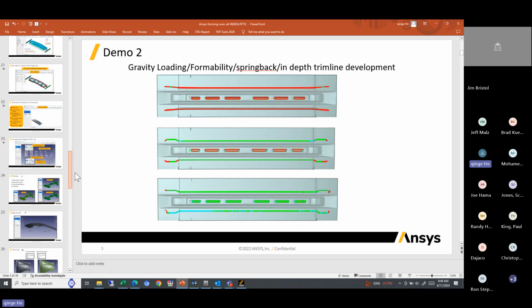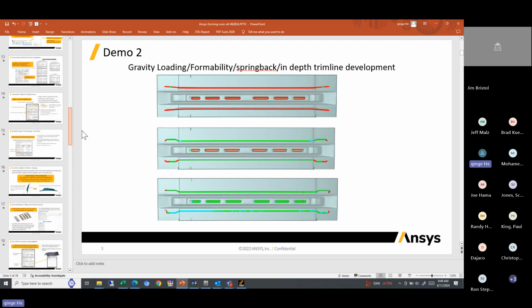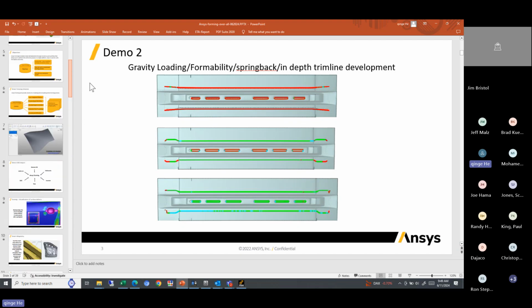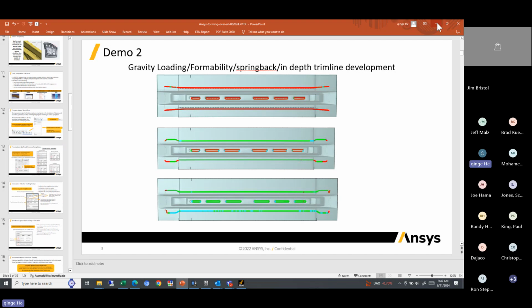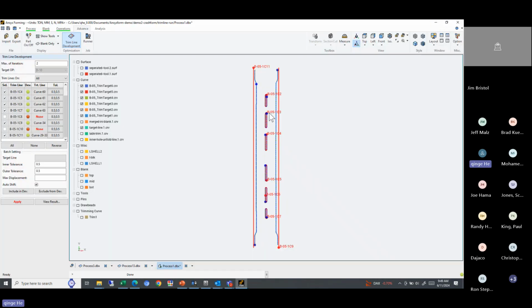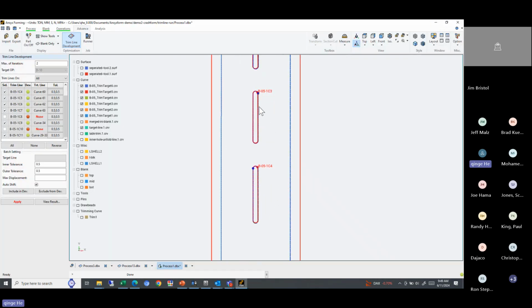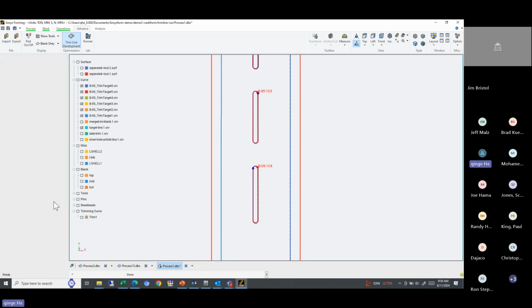So AutoShift basically looks for that square and then matches it. I think I used it wrong. It's going to use the calculation: it calculates the center of the target closed area and the center of where you're at, and looks for the center and moves them together. So this function, AutoShift, will give you that, which will make the development faster, especially for the inner trim.